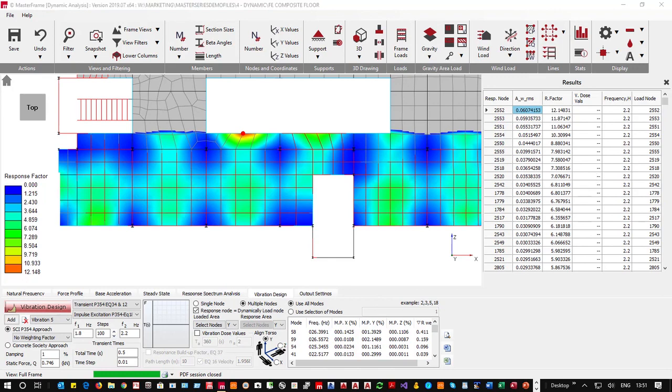Does the mesh size help in your analysis? Yes and no in 2 ways. A coarser mesh is going to get us analyzing things a lot quicker, but may not be as accurate. I think you're really looking at dividing members into 1, 2, 3, 4, 5, 6 components roughly to get a mesh.